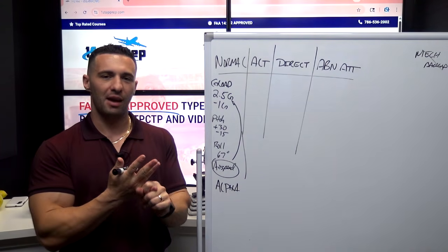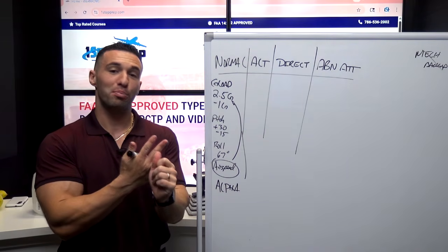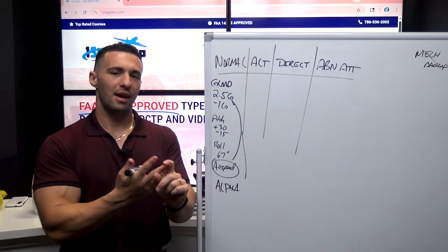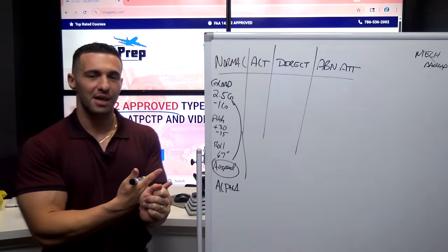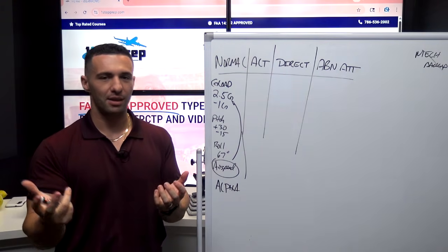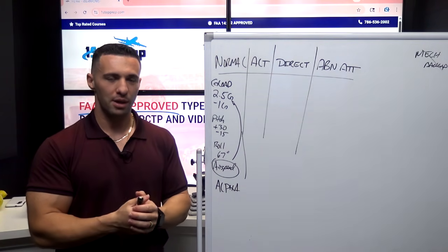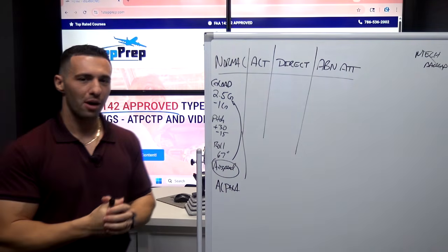So the first A of ASAP is autopilot disconnects. The S is the spoiler stow. The second A is angle of attack is commanded by the side stick as opposed to G load, which is technically in normal law the relationship that we have between side stick and ELAC. We will dive into that here shortly. And then finally the pitch trim freezing in the nose up direction. That's alpha prot right there in a nutshell.